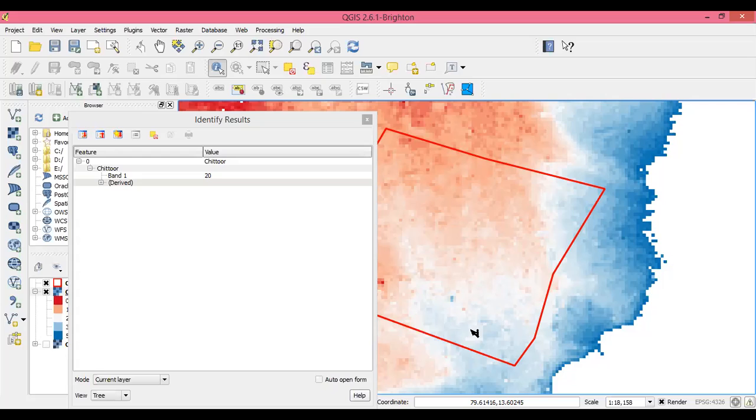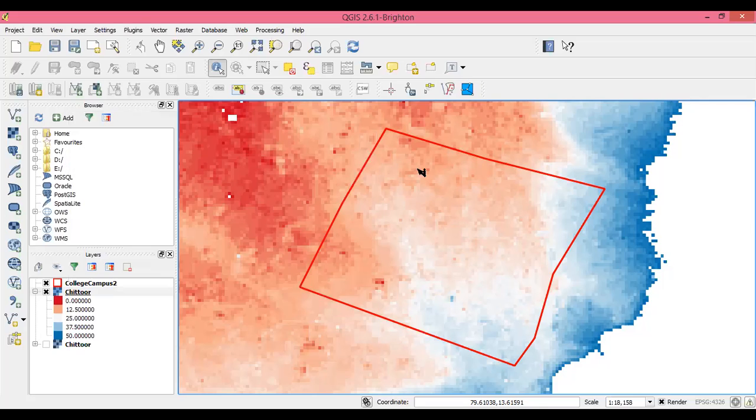So you will try to find out what the slope inside your watershed is. You can find the average slope. This particular region happens to be some kind of an up and down region. So it's not very clear if there's a slope in one direction. It may be sloping up and down in different parts of the watershed. So in that case, you are better off trying to find the average slope that you expect in this kind of a region. You can take the two extreme corners of the watershed, find the elevation difference, and find out what the slope would be, right? So that's one way of doing it.